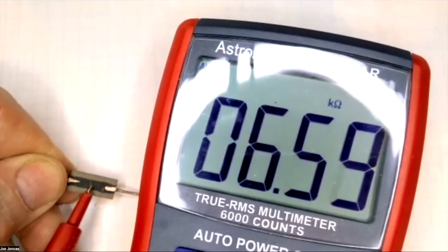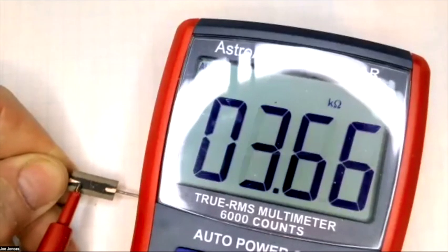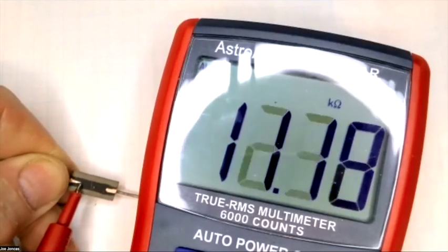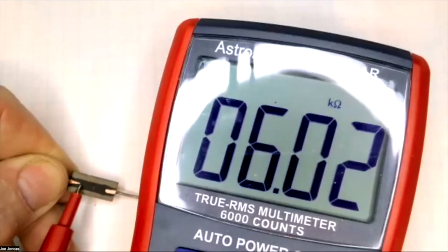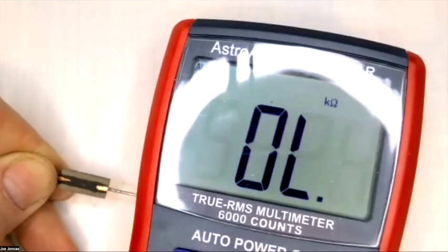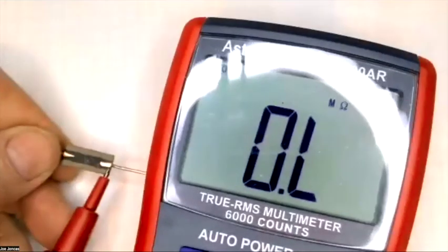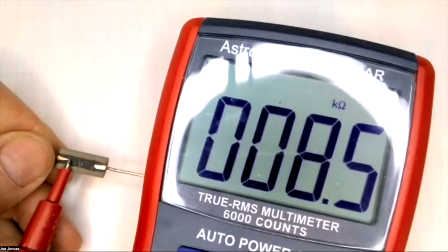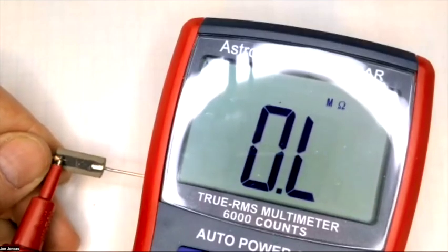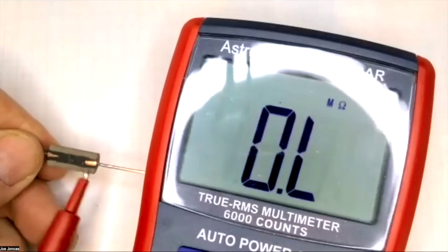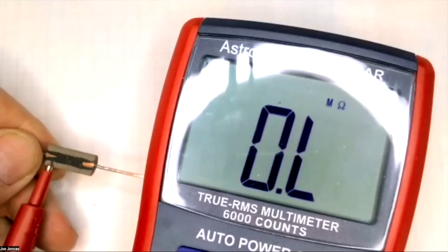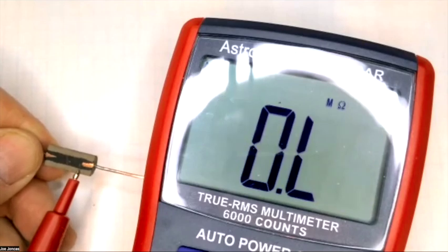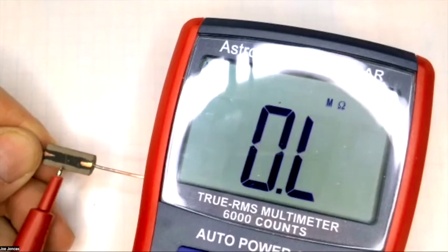Okay, that's cool. 7,000 ohms. And then as I move down here, I get down at this end. Come on, don't make a liar out of me. 6,000 ohms. You can see as I go across the carbon here, it gets less and less as I go from this end down to this end. But there's just carbon in here, like pencil lead. And that's how resistors are made. They have carbon built up that has X amount of resistance per length.